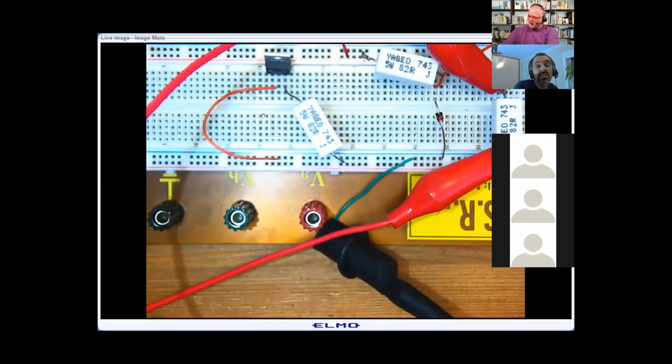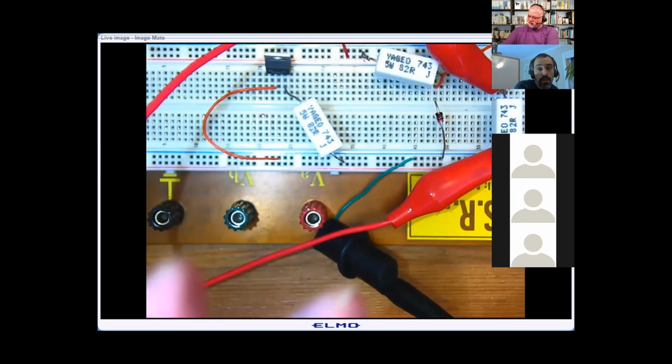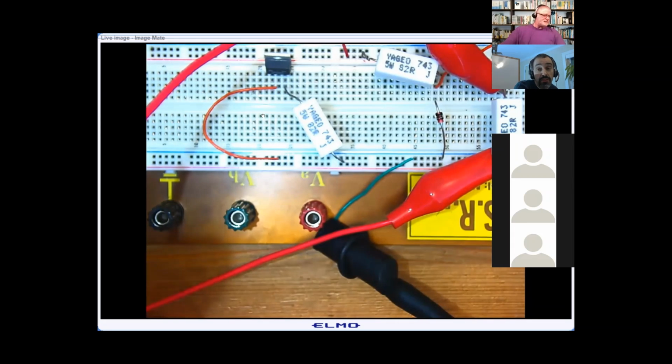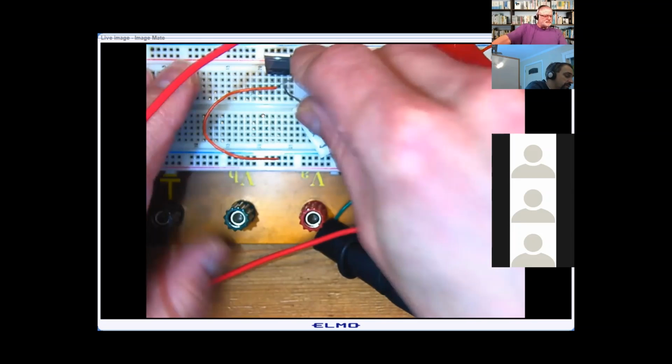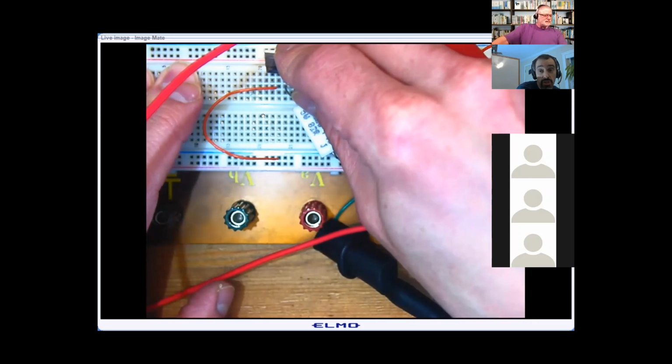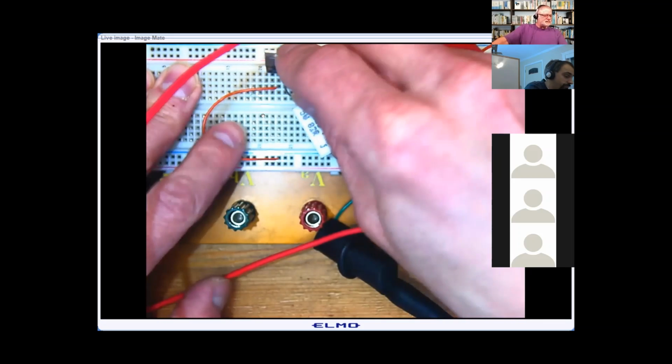So, for example, we want a 6.2 voltage reference, and this is checking to see if our power supply is working correctly. So we'll measure the voltage across it for that reference voltage, and we'll bring it to a comparator. That comparator will go to a processor and say, hey, if I drop below this, we've got a problem. We'll shut down the circuit. So a lot of times our Zeners are not used really for loads. So just to give you an idea on that one. They can be for cheap things, but when it comes to precision and some high current things, no.